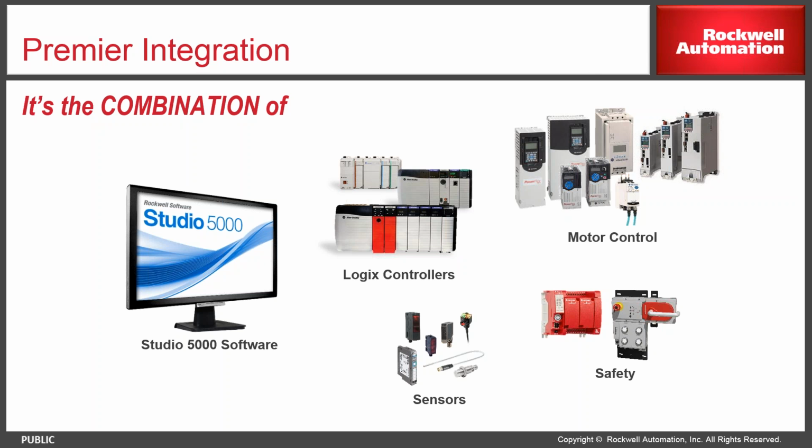So through the analytics of the data that you get, you are able to do a predictive maintenance. You can predict which field device is reaching its life cycle, and you can plan a replacement of that product before the line stops. You can reduce the mean time to repair, okay, and you can have full access to the device data. So it's a more efficient use of the site personnel.